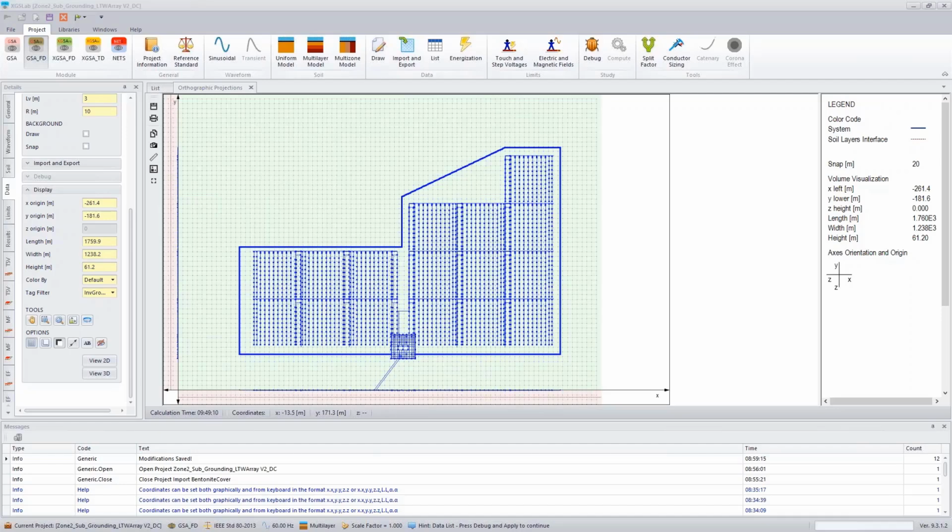And one other thing I wanted to mention in this presentation is that the approach shown here is one methodology for performing a grounding system analysis for these large photovoltaic systems. There are various approaches. Mine was modeling those auxiliary grounding systems, those solar posts, as high density in the areas that I'm looking in. You can approximate other portions of the system using lumped impedances, or you can model the entire system if your software is able to do that.